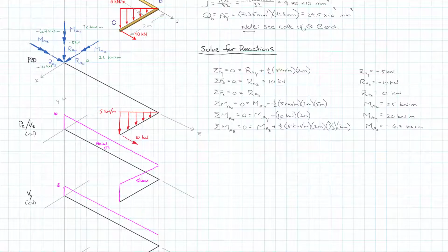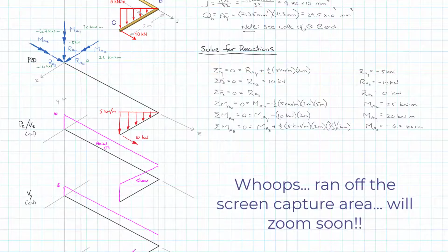So having arrived there, of course, as we turn the corner and go between B and C, the triangular distributed load, which is ultimately what caused this, is now going to start to reduce it to zero, and it will do it at an increasing rate, so that linear relationship between B and C on the load intensity diagram becomes parabolic as we connect up to our diagram there.